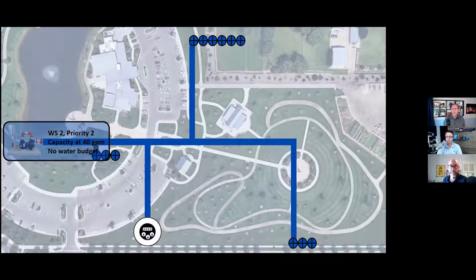So if they're going to do the pond first, the condition in which to switch water sources would be what we call an empty condition. So when the pond drains down to a certain level, we're going to consider it empty or no longer use this water source. And we could do that with a soil moisture sensor, a pressure sensor, or any other float switch, mechanical float switch. It just needs some condition to tell it when it's empty to a certain level. And the same thing could be said about your domestic. The condition was gallons.